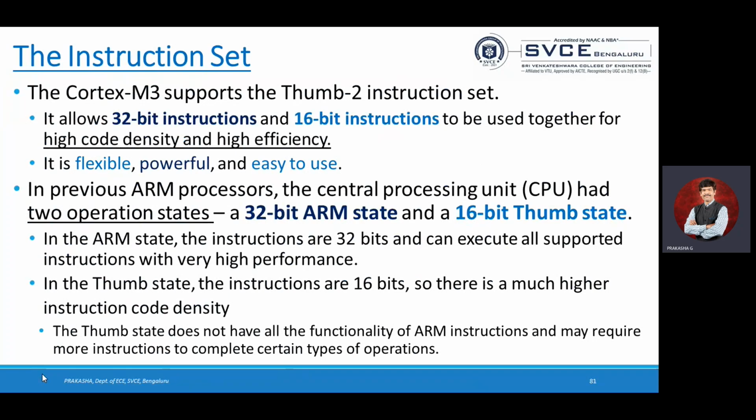The labels should be at the extreme left side of your screen. If you keep them here, then you are going to get the error. That's why, see, I have done the LDR here and the label I am writing on the left hand side. Even you are going to have the start, you are going to have the end. So start should be at the leftmost side of the window. You may have one more thing, entry. All your labels should be on the extreme left side of your editor window.